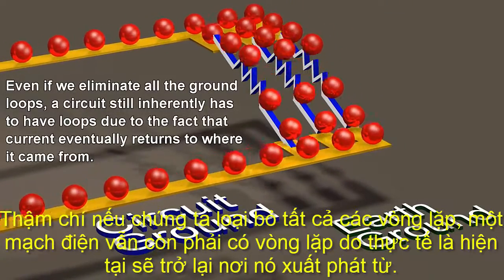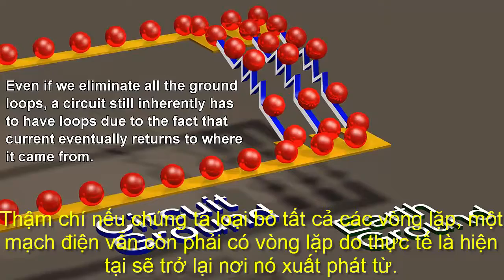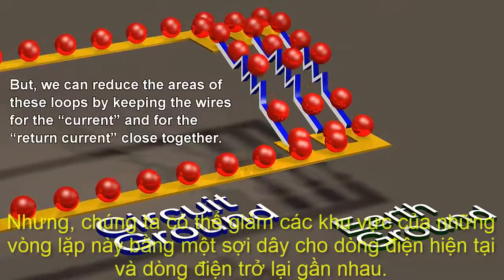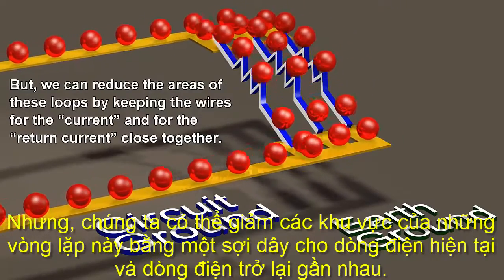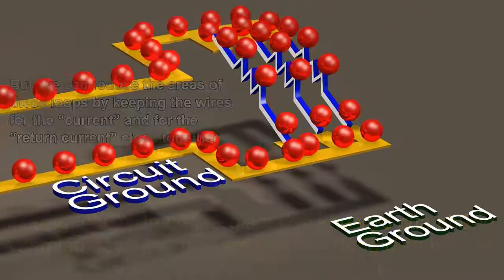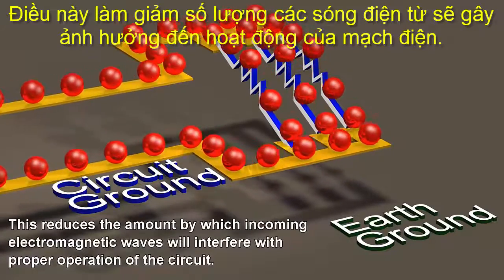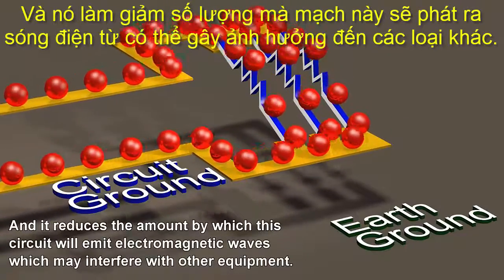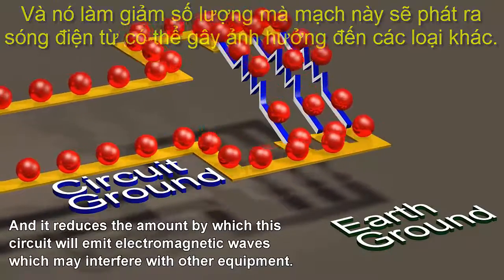Even if we eliminate all the ground loops, a circuit still inherently has to have loops due to the fact that current eventually returns to where it came from. But we can reduce the areas of these loops by keeping the wires for the current and for the return current close together. This reduces the amount by which incoming electromagnetic waves will interfere with proper operation of the circuit. And it reduces the amount by which this circuit will emit electromagnetic waves which may interfere with other equipment.